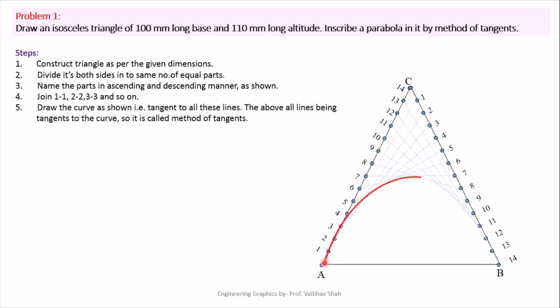After that, we'll just simply join this outer periphery of your tangents to get the smooth curve, and simply join another outer periphery. So as you can see, this profile of the parabola is already traced out by these tangent points. So you have to just completely highlight this parabola with a dark line. You will start joining from your point A on the inner side of this profile traced out by this line. So let us join this by a dark line and you will have this parabola.